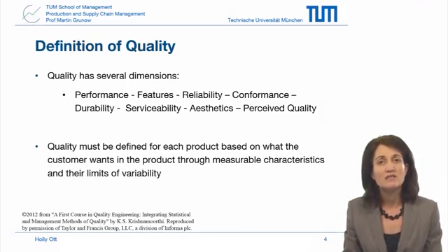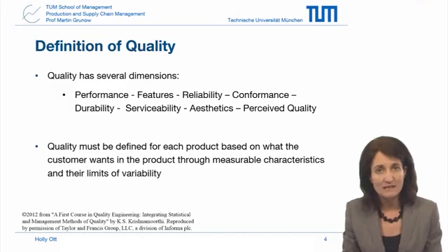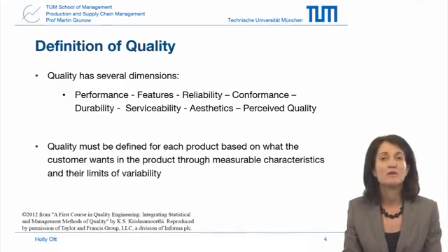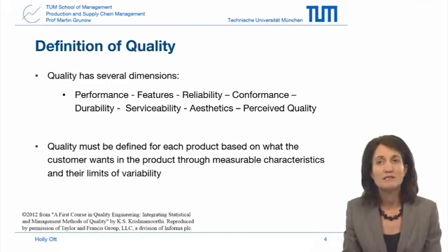And the targets and tolerances together the designer has come up with are called the specifications, or the specs for these characteristics. And this is what we're going back to now. We're going back to the idea of product specifications in order to talk about the capability of a process.